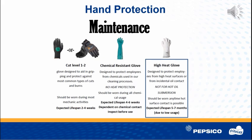A chemical resistant glove is designed to protect employees from chemicals used in our cleaning processes. No heat protection. Should be worn during all chemical usage. The expected lifespan is 4 to 6 weeks, depending on chemical contact, and inspect before each use.